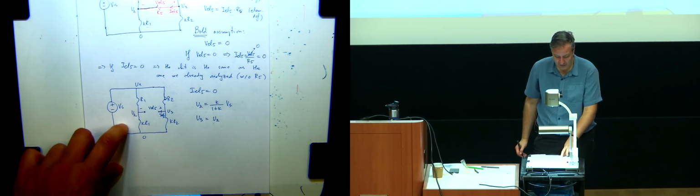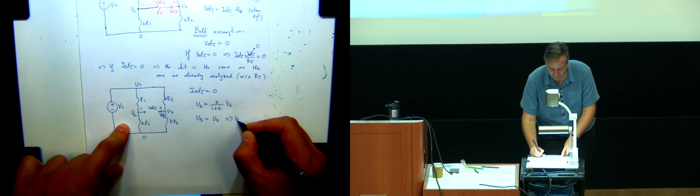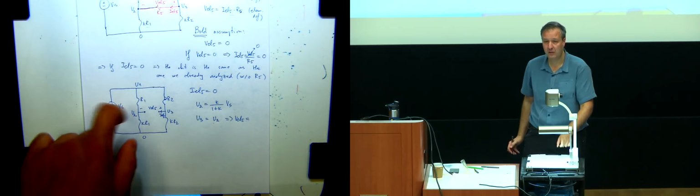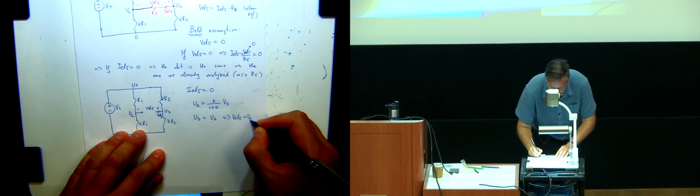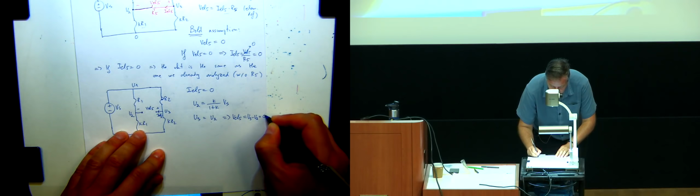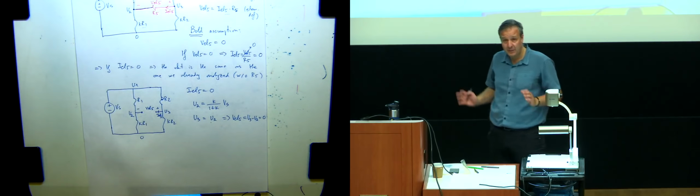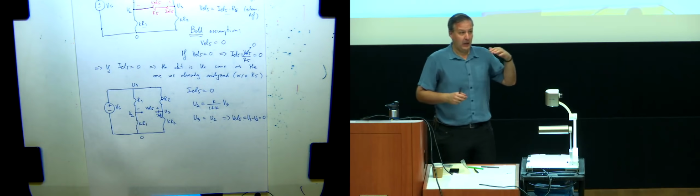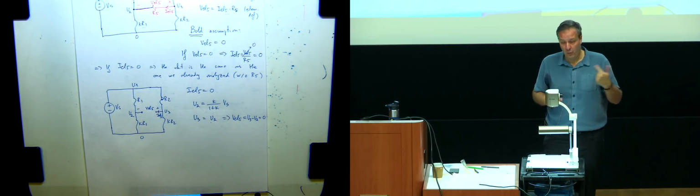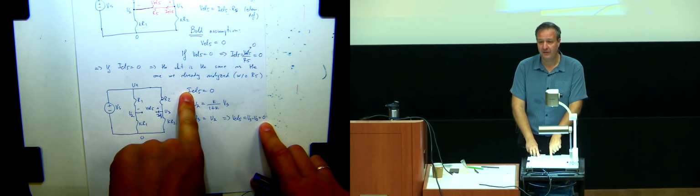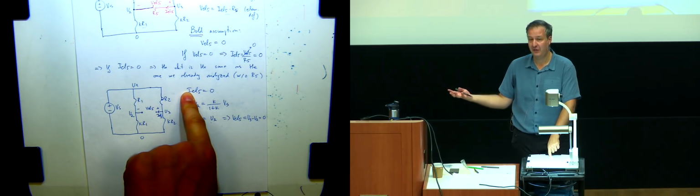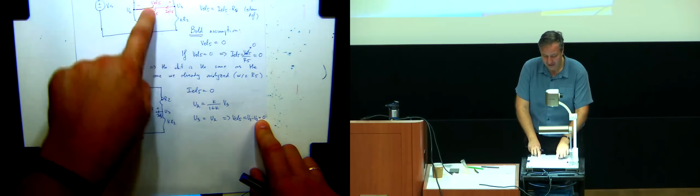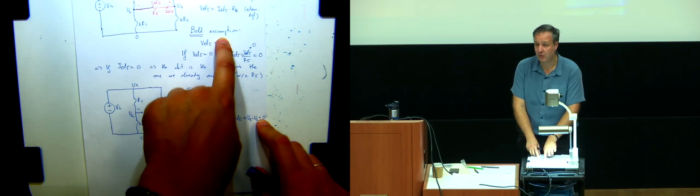Well, okay, if U3 is equal to U2, what is V element 5? Voltage. Yeah, or more formally, it's U3 minus U2, and that equals 0. Does this make sense? So, we started from I element 5 equals 0, and we derived that in that case, indeed, V element 5 is 0. Right? So, that means that in this case, my assumption was correct.